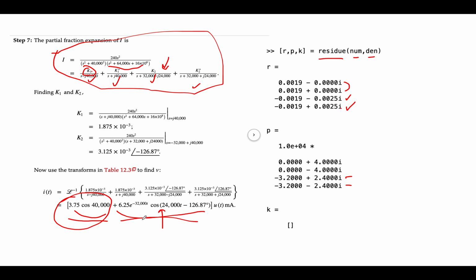But if you want to incorporate the transient effects, you can only get that when you use Laplace. And so what the Laplace method shows is there is this exponentially decaying term that is a function of the values of R, L, and C. And this will die away. This one won't. So eventually a phasor analysis would be great.